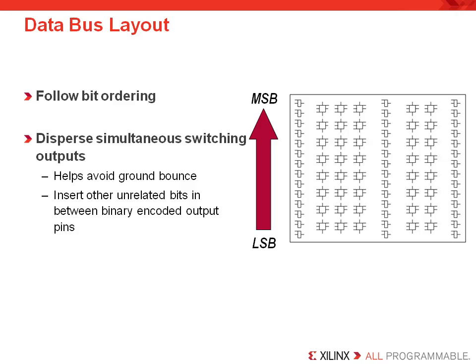One of the most important concepts to remember about FPGAs is the carry logic resources propagate the carry signal vertically. This implies that the least significant bit be placed below the most significant bit and hopefully will follow bit ordering. This also must be followed for pin assignments. That way routing to or from associated logic that uses carry logic will have a minimal routing delay.